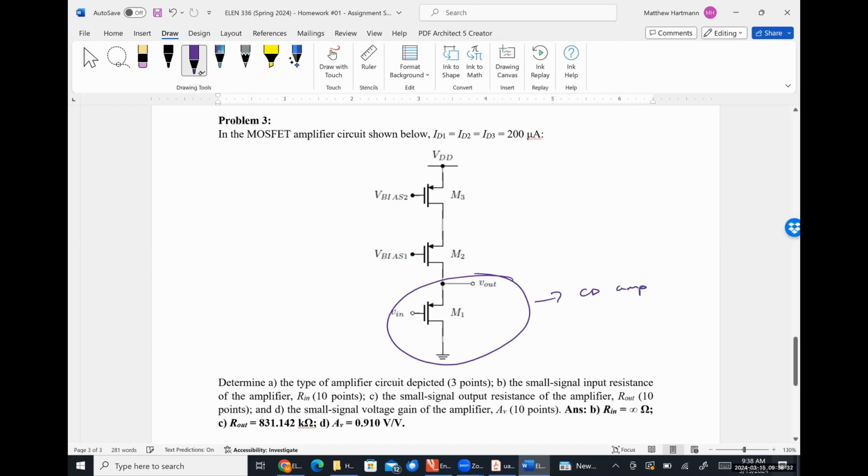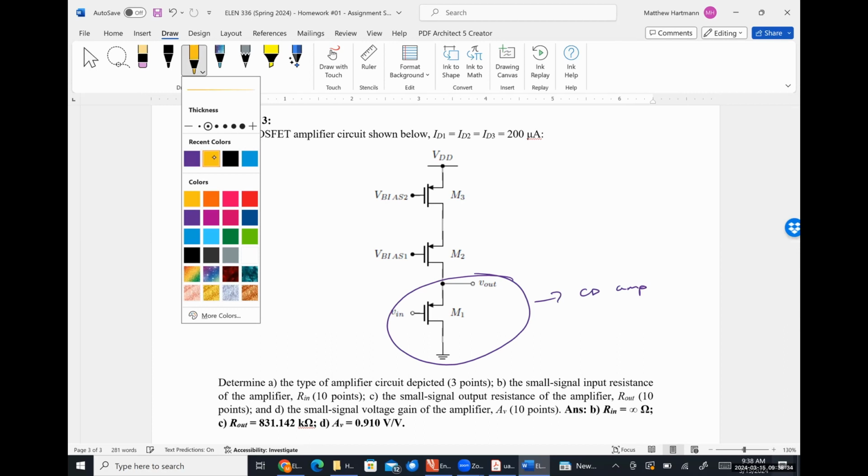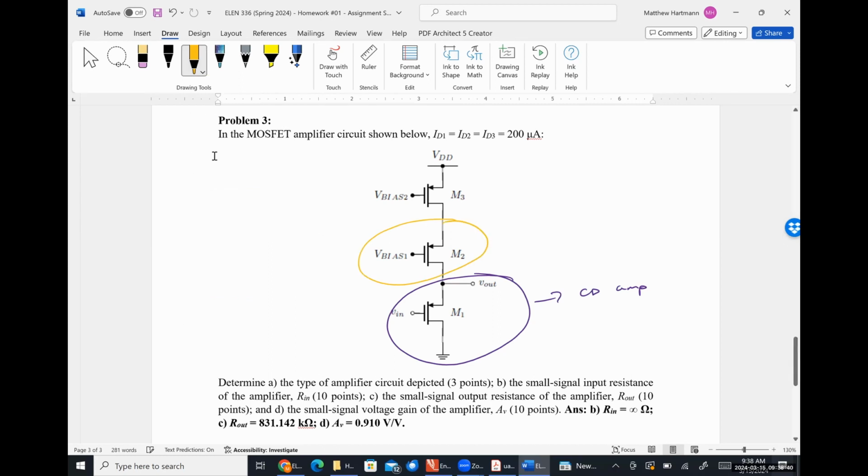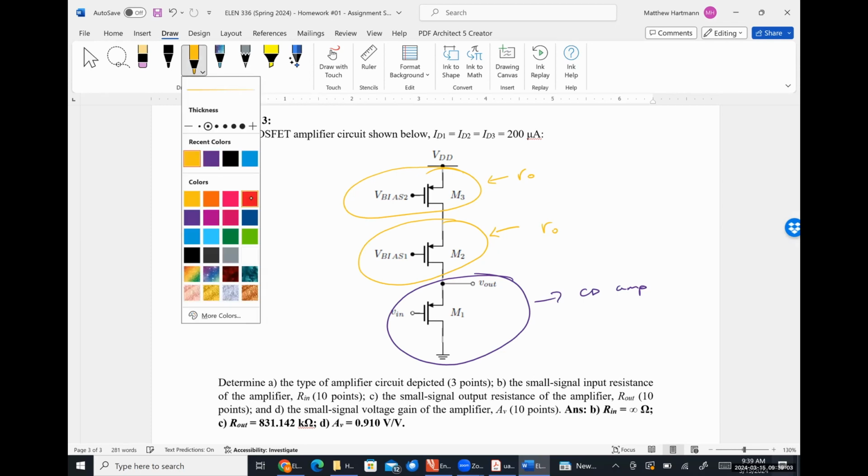And then this bit up here can potentially be difficult. So this guy right here is a PMOS current source, effectively, right? So it's going to look like just R naught P. But it's effectively being degenerated by another one. So realistically, the easiest way to do it until we learn about cascodes in a couple of days, because this is actually an example of a cascoded current source,